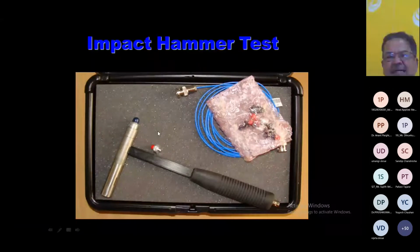The other thing is the impact hammer test. I told you that in the first test, the free vibration test, we applied a displacement and your structure vibrates on its own elastic property. Now we apply an impact. This is the impact hammer, and here the sensor is placed.